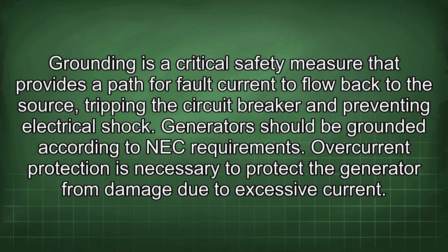Grounding is a critical safety measure that provides a path for fault current to flow back to the source, tripping the circuit breaker and preventing electrical shock. Generators should be grounded according to NEC requirements.